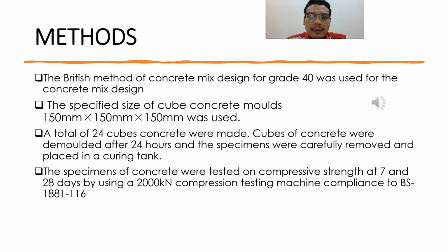Cubes of the concrete were demolded after 24 hours and the specimens were carefully removed and placed in the curing tank. Then the specimens of the concrete were tested on compressive strength at 7 and 28 days by using a 2000 kilonewton compression testing machine compliant to BS 1881-116.